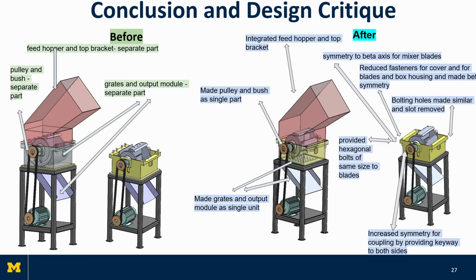Design critic. Here is our design before and after. We integrated the feed hopper plus top bracket, combined pulley plus bush, and merged grate plus output module. Also we redesigned blades and mixer blades for better symmetry, standardized all fasteners to hexagonal bolts, and increased symmetry on the pulley, box housing, and blades.